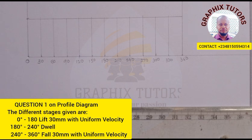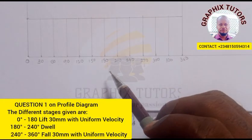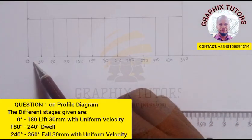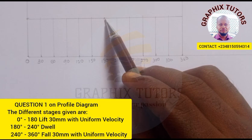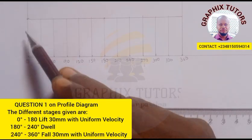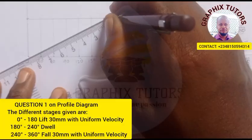Now the next thing is, the question says it rises or lifts from 0 to 180. Since we are dealing with uniform velocity, for me the word uniform velocity will just be a straight line. So it moves from 0 to 180, and this is the highest point. This is how it rises to 30. So it moves from 0 to 180 with a lift of 30 millimeter, right? From here to here is 30, and this is 180 to this point. So I'll just take my instrument and draw a straight line this way.